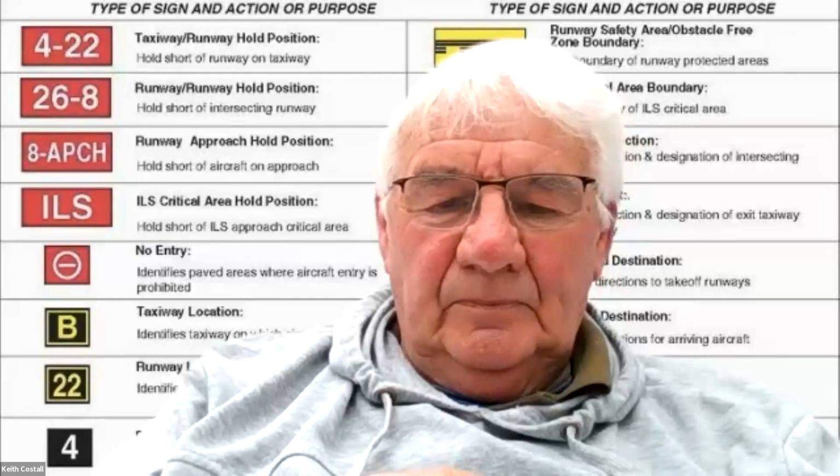Yes. I've got a question here. After runway surface relaying, the runway centerline surface level at PAPI is 15 to 19 centimeters higher than previous levels, and somewhere I read that a 30 centimeter height variation is allowed. Please inform me, do we need to elevate the PAPI by increasing the leg height by 15 to 19 centimeters? Probably this is something that would need to be, I don't know.